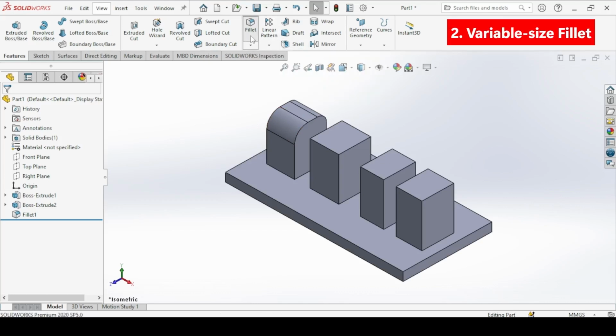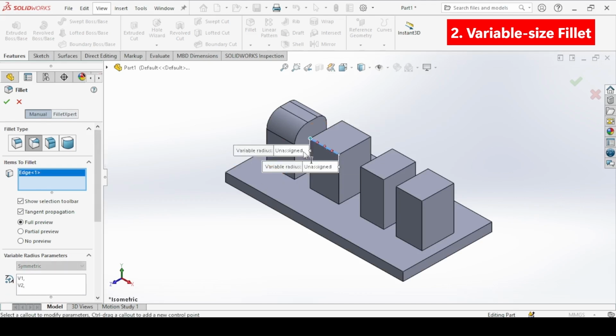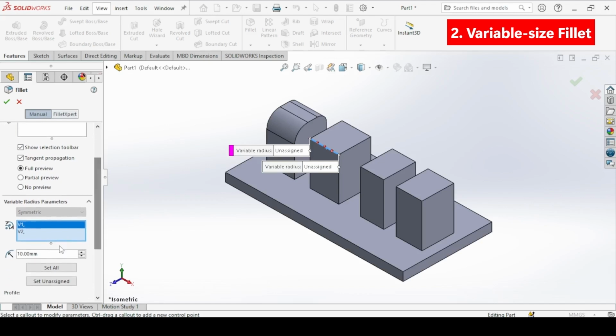The second type of fillet is the variable size fillet. So with the variable size fillet, you need to select again an edge. So click on this edge, and we can see there are 2 different variable radii we can select. So the first variable sets the value to 10 millimeters, and then the second variable sets the value to 20 millimeters. And we can see the radius transitions from 10 millimeters smoothly into the 20 millimeters.